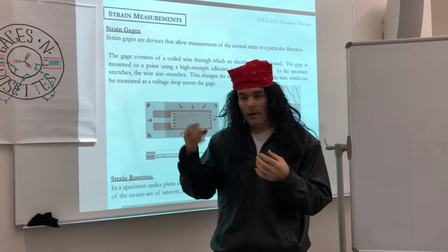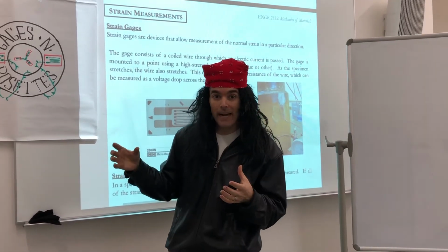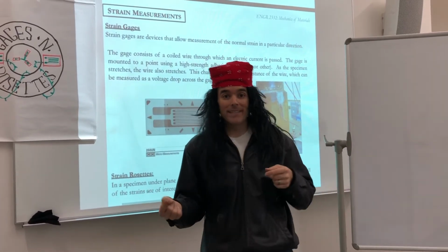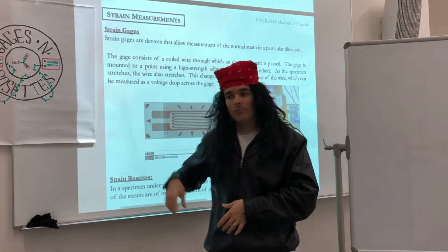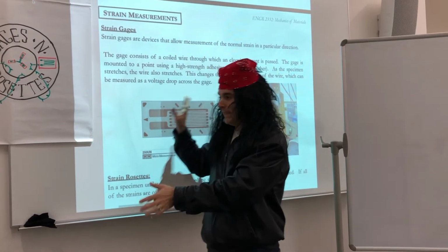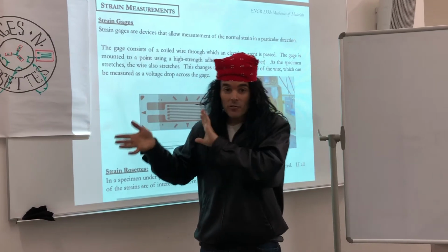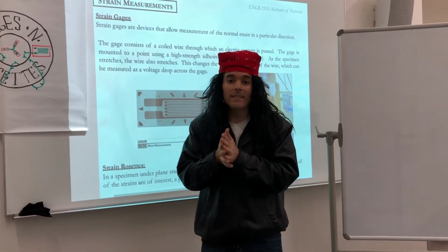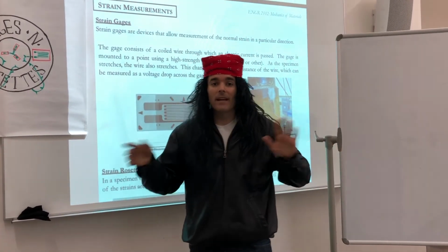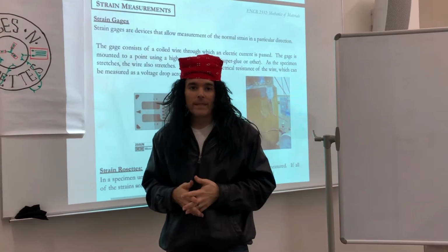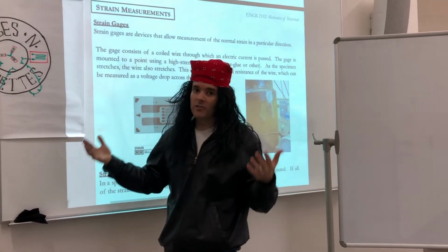Once we solve and are able to determine the strain at a particular point, we can always then use our mechanics equations to find stress. We can do plane stress, we can do plane strain depending upon the case. We can do transformations, principal stresses. We can check if failure has occurred. It gives us a variety of tools to check the real-life performance of engineering systems and structures.